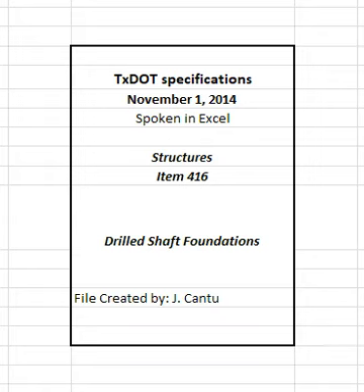Provide workable concrete that does not require vibrating or rodding. Vibrate formed portions of drilled shafts. Place concrete continuously for the entire length of the shaft. Limit free fall of concrete to 25 feet for dry shafts of 24 inches or smaller diameter. Use a suitable tube or tremie to prevent segregation of materials. Use a tube or tremie in sections to provide proper discharge and permit raising as the placement progresses.